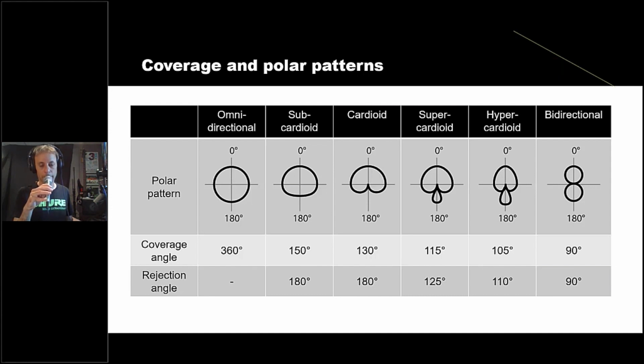But again, I'm going to go all the way back here and try to keep the gain coming up, and you should hopefully hear a much different characteristic in the low end, and that's what proximity effect is. It's an effect, it's not designed in, it's a side effect of having a directional microphone. All directional microphones have this. Omnidirectional mics do not. It doesn't matter what the distance is from your mouth, the frequency response does not change.